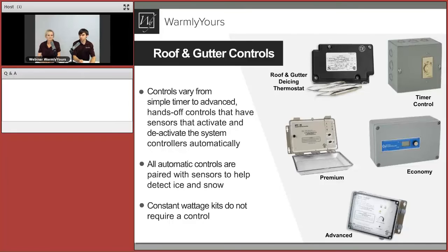What it will do for you is give you a good manual control. You manually turn it on for the amount of hours you need, and the system will shut off after that amount of hours. So anytime you specifically need to make sure the system only runs when you ask it to run, that's your perfect scenario. But once again, that's just the case where the application requests that manual control. And this is the only control that does not have a sensor combined with it. That's correct. It's just on a timer, and that's it. That's the only non-automatic control, I would call it.